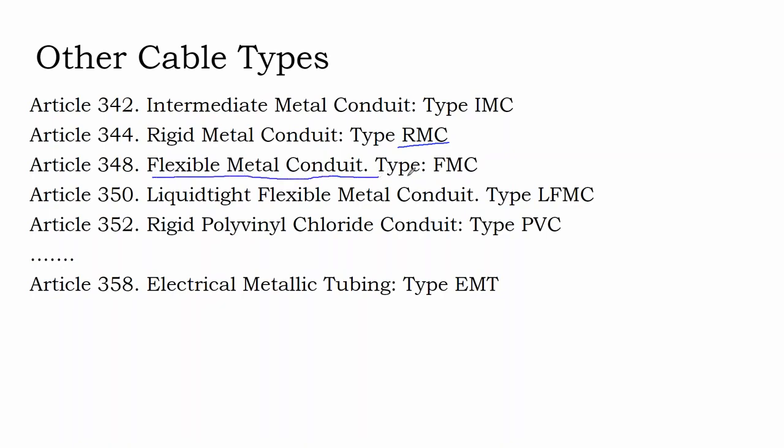There's flexible metal conduit. It looks like metal clad cable. We were talking about it earlier. Then we have this liquid tight flexible metal conduit, and that's pretty useful because it's metal, and DC wiring, solar cable has to be in metal when inside a building.